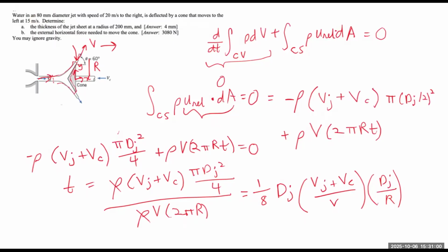And Bernoulli's equation has several assumptions. It assumes steady flow, no friction, meaning that viscous effects are negligible, that it flows along a streamline, and that it is incompressible flow. So we can apply Bernoulli's equation over here to find V.